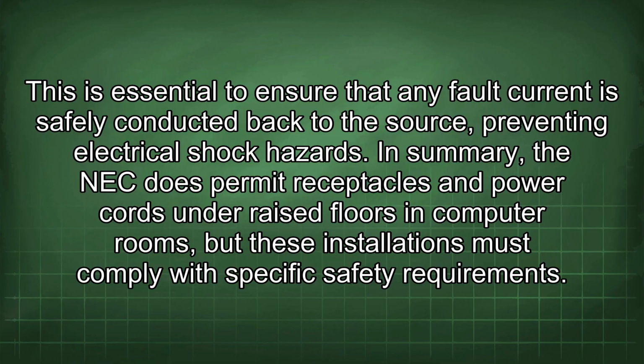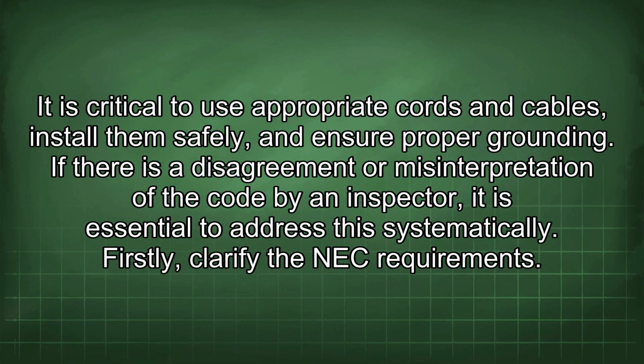In summary, the NEC does permit receptacles and power cords under raised floors in computer rooms, but these installations must comply with specific safety requirements. It is critical to use appropriate cords and cables, install them safely, and ensure proper grounding.